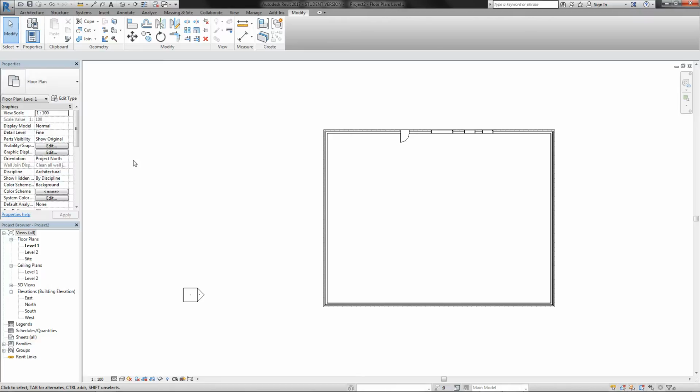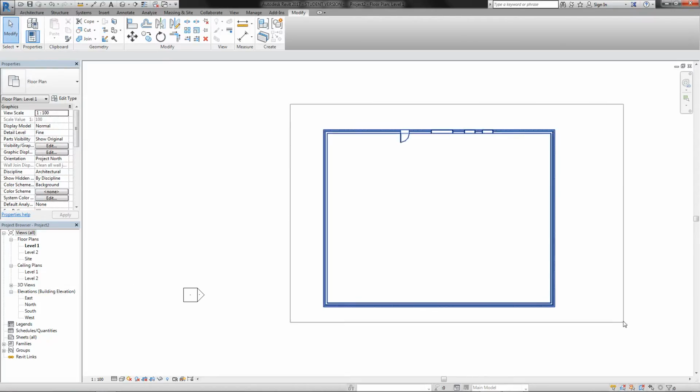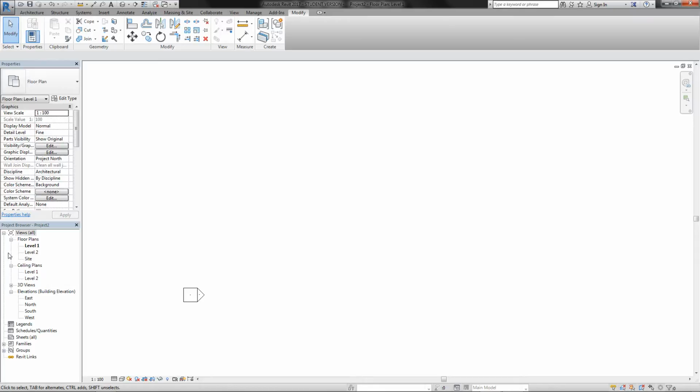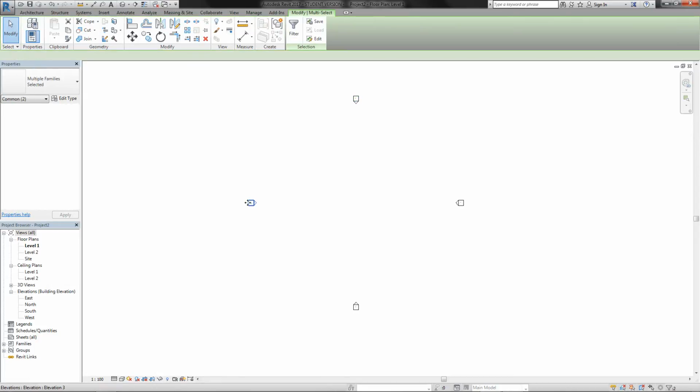All right, so that's about this part, and then I'm going to show you guys how to actually define a project. Usually the first thing we do is go to elevation and define the levels we have in our project. You will also see some things that you're not supposed to delete, like these, which mean you have an elevation there. You might have section lines or anything else, so make sure you don't delete them. There are ways to hide them and lock them, so if you're not comfortable that you won't delete them, lock them or hide them.